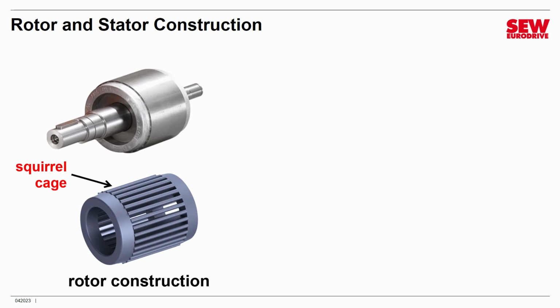What it really is, is a giant coil. All those metal bars connected at the end are like a big electromagnet coil that has both ends shorted together. We call that the squirrel cage because it looks like the thing you find in a rodent cage of some kind, that your hamster would run around on. And the squirrel cage magnetically interacts with the magnetic field produced by the stator, and that's what causes it to turn, and of course it turns the shaft.